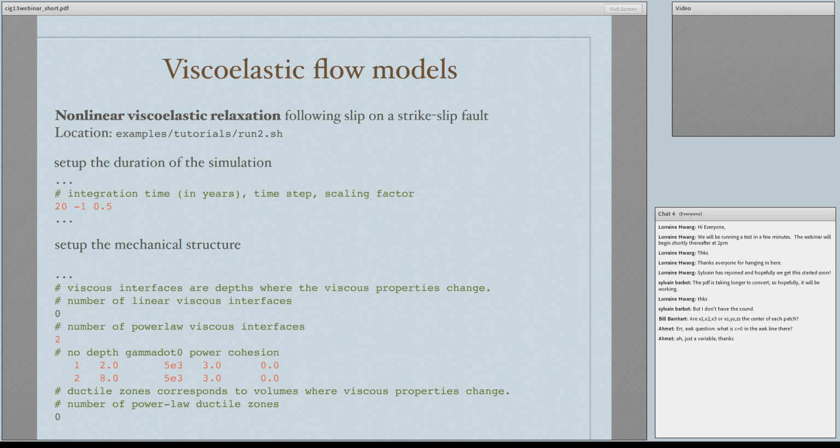You can also provide your own time steps, and the output will be only written to disk at the times you provided. But in fact, internally, it will do calculation at smaller time steps if needed, just to ensure accuracy. So these numbers are not that important. Basically, you're often guaranteed to have a good computation, even if you change these numbers.